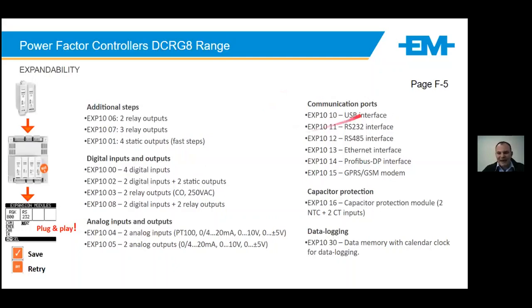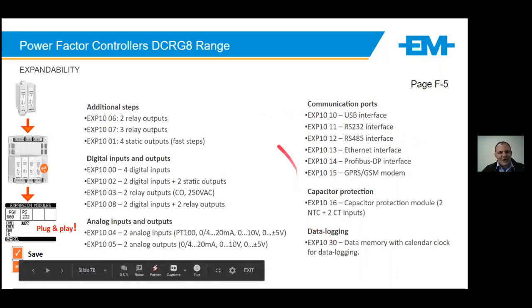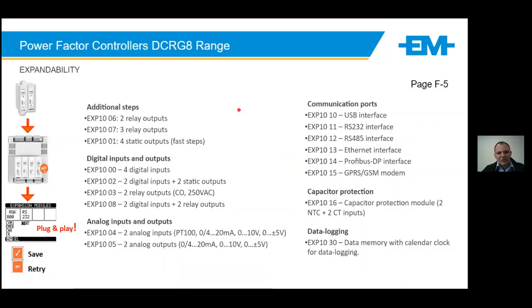All right. Quite important, more and more customers want visibility of their systems on the network, on their SCADA, in the cloud. These controllers do have all the necessary expansions to be able to do that, be it RS485 Modbus or Ethernet, Profibus, and modem capability to extend that function. The controller can also take the data logging module, which will allow you to log specific variables at a specific interval for audit purposes.